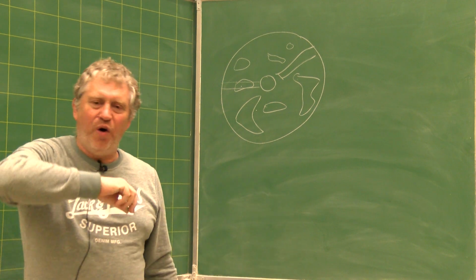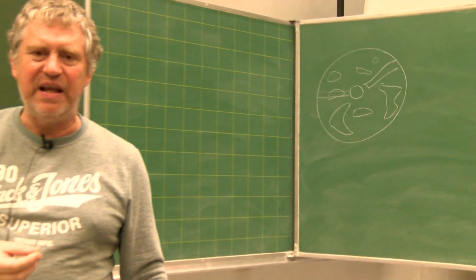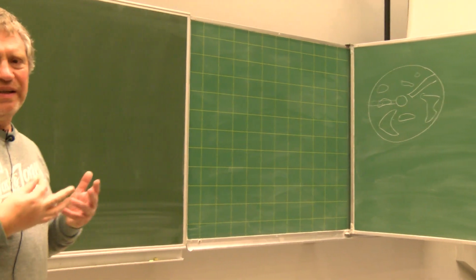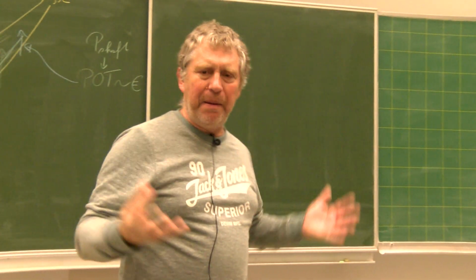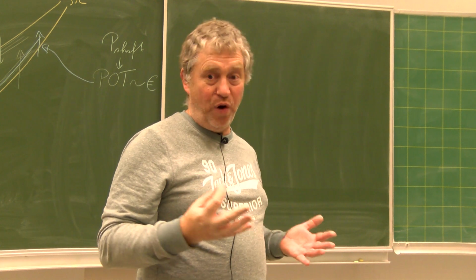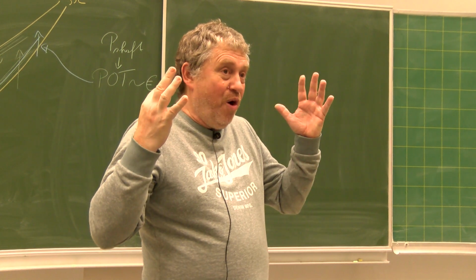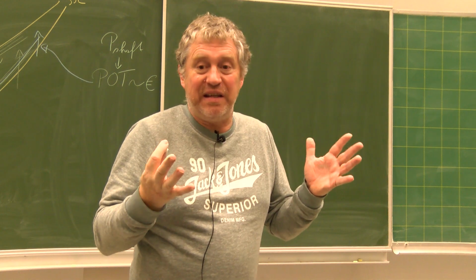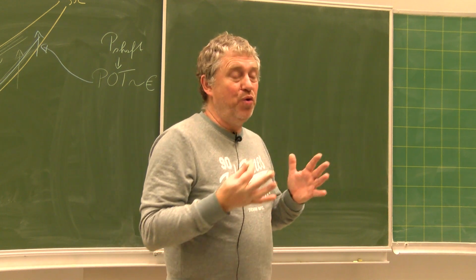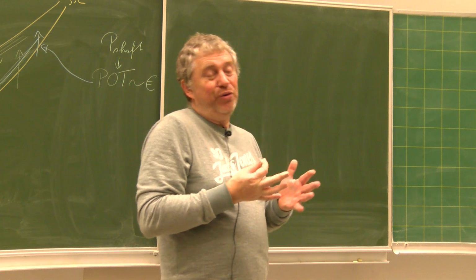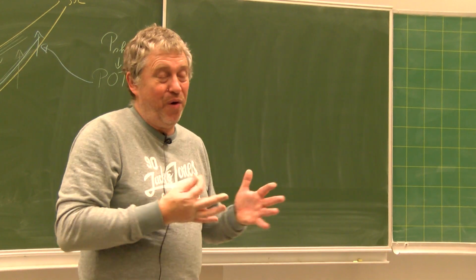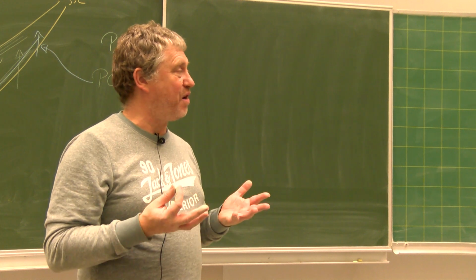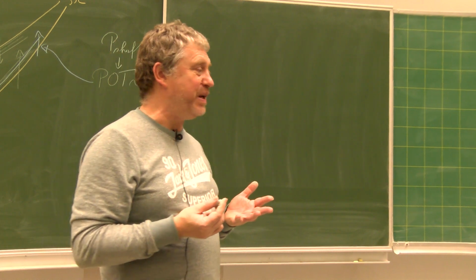You see that over 360 degrees, the blade is seeing regions with different parameters, different orientation of the flow, and mainly we know a problem with the axial velocity. Due to the mass flow rate or the orientation of the flow, it can be one of these two reasons or a combination of the two.